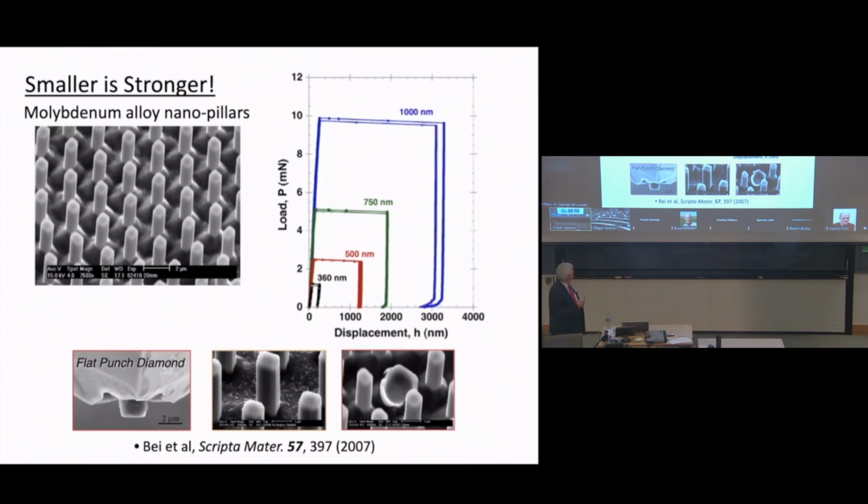And the moly grows as these fibers that are then embedded in a nickel aluminide matrix. And with preferential etching techniques, you can remove the matrix. You just chemically treat it, the matrix goes away, and you end up with an army of little pillars like that. And you can control the size of the pillar by controlling the directional solidification